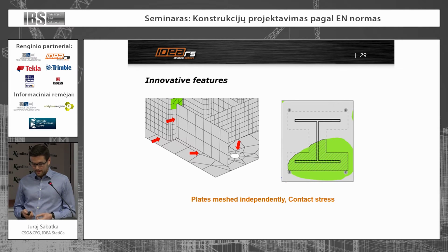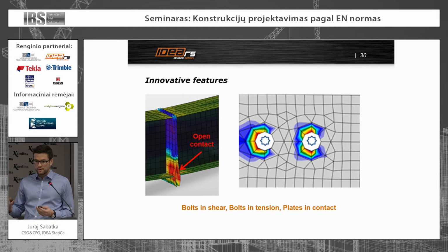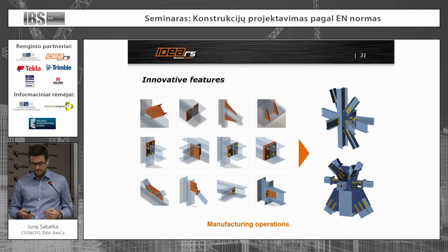We also came up with a new model for the concrete, the contact stress between a base plate and a concrete block. The big topic was the bolts. That's in the majority of connections a weak spot. So we were thinking about how to model the contact between the two plates, and then how to properly analyze how the bolt is pressurized, what the impact is. So we have a new model for that as well.